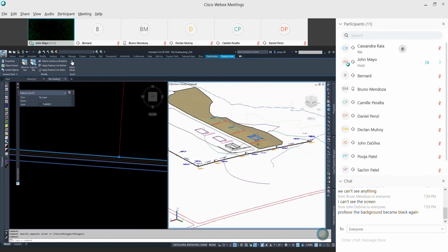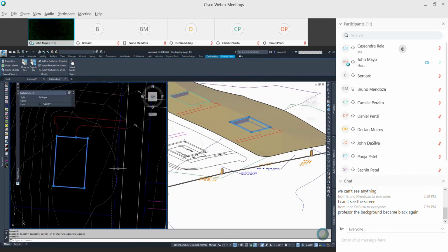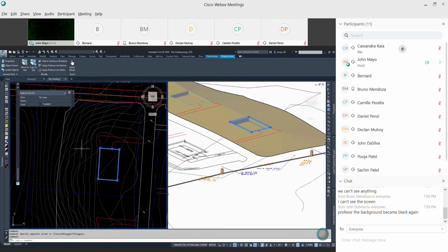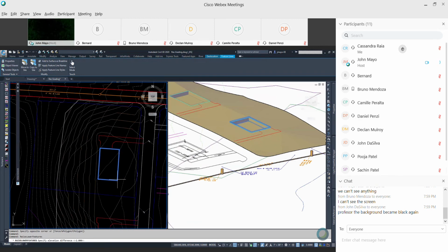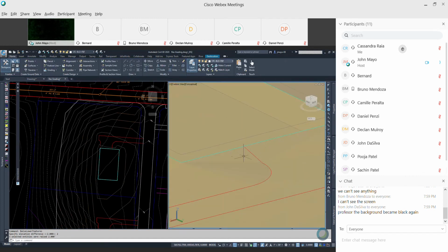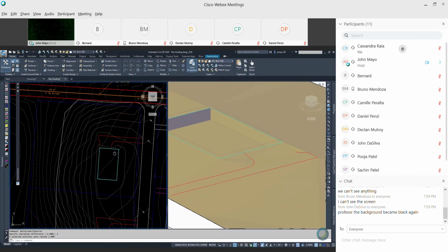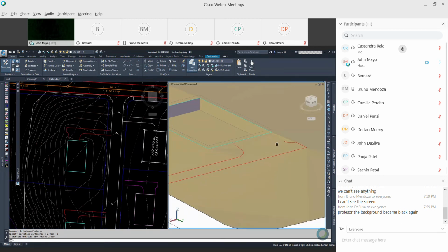Let's say that 379 was too low, and it might be too low because I really only have one contour back here. But I don't know. I'm going to try raising the whole building up 2 feet. And it comes up, and you see my break line follows. That's because they are in the same site. So when you're using these feature lines, depending on your style, you can give them different styles, but make sure they're in the same site when you begin grading so that they are reacting together.